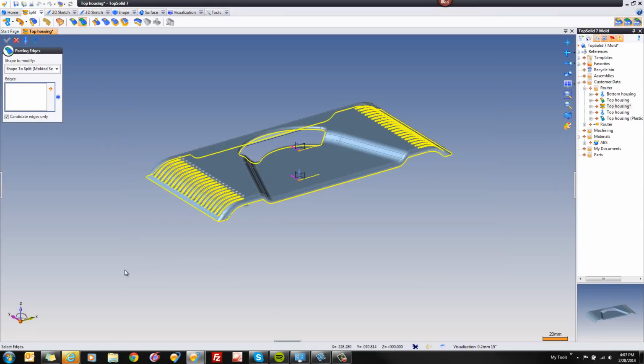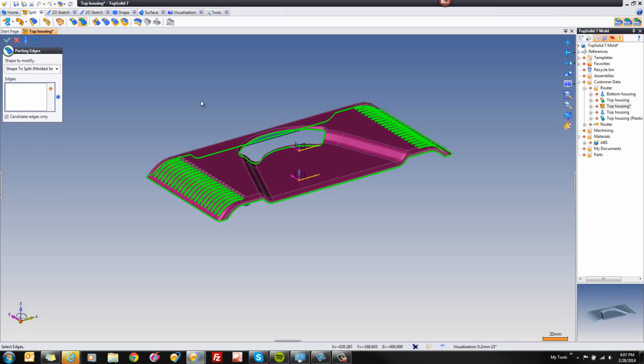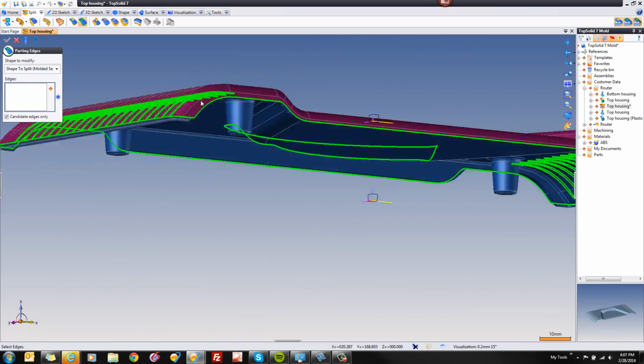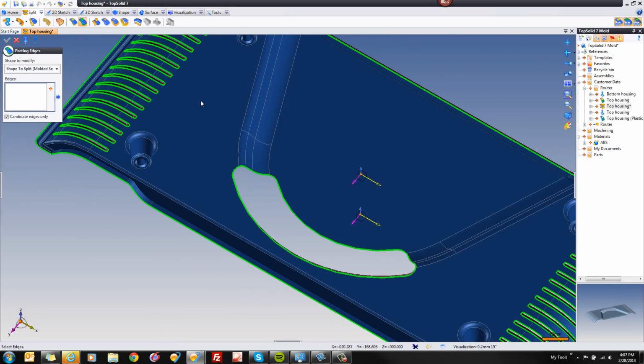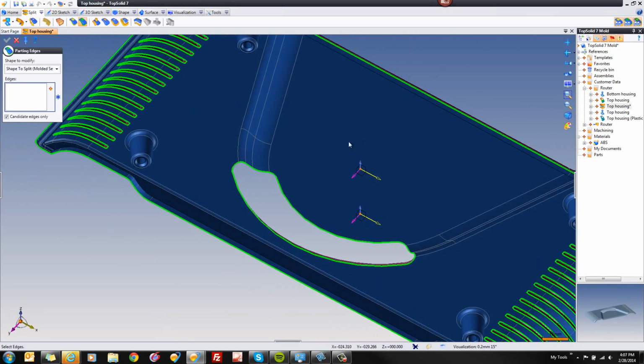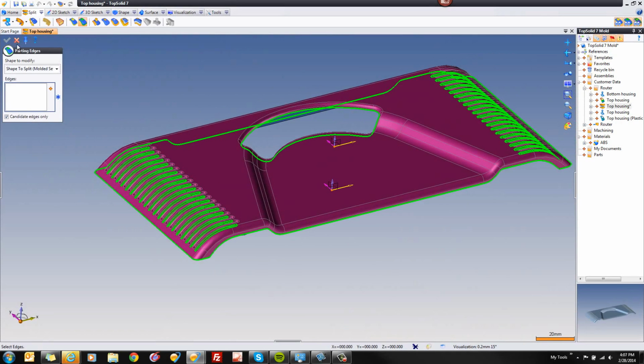And to do so is really, really hard. I'm simply going to Windows select and grab everything. Now, as soon as I validate here, watch what happens. Here, the part just changed color. And in fact, because we got all the parting lines right at the first go, the software automatically did the split. So the blue is our core side, the purple is our cavity side.